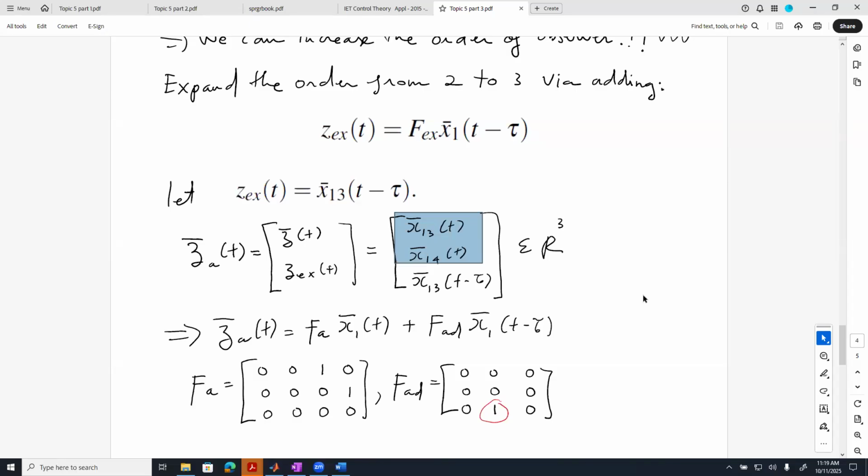We wanted to estimate these two variables. We couldn't do it because it resulted in an unstable observer, a second order unstable observer without internal delay. And we said, look, we're going to estimate a bigger generalized functional. That's no longer two functionals, but three. Once we can estimate this augmented generalized functional, of course, to realize these two, it's just a subset of that one.